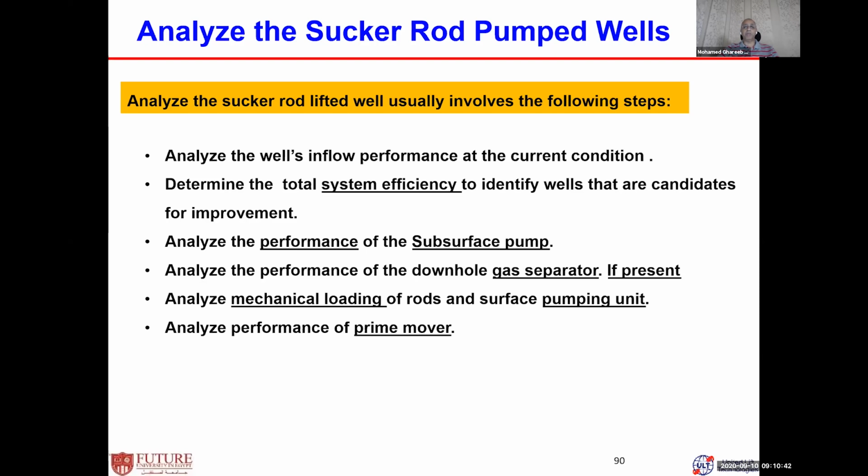One of the most important subjects is to always analyze my subsurface rod pump, how it's working, how it's running. Remember, this pump is purely mechanical. All valves are steel, some type of alloy steel or stainless steel, whatever; every type of downhole equipment is mechanical. With time, can we have wear and tear on all those mechanical parts, that mechanical equipment?